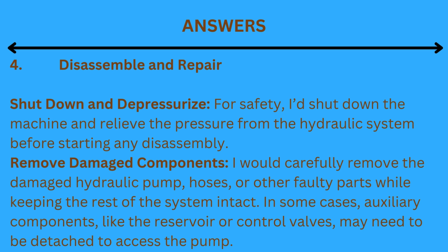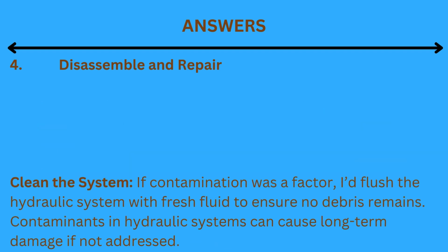Remove damaged components. I would carefully remove the damaged hydraulic pump, hoses, or other faulty parts while keeping the rest of the system intact. In some cases, auxiliary components, like the reservoir or control valves, may need to be detached to access the pump. Clean the system.